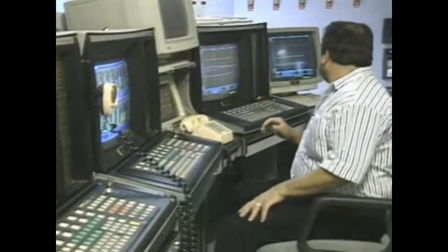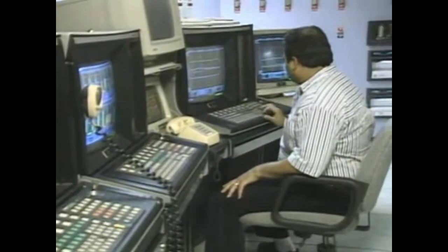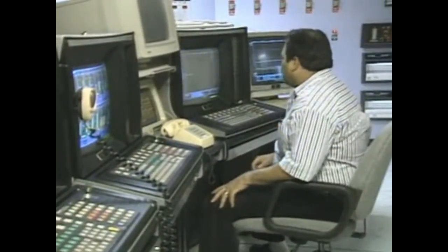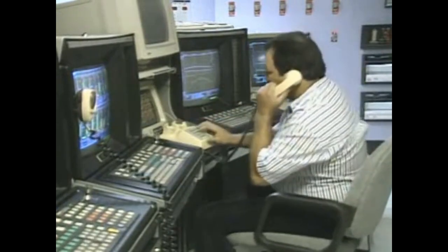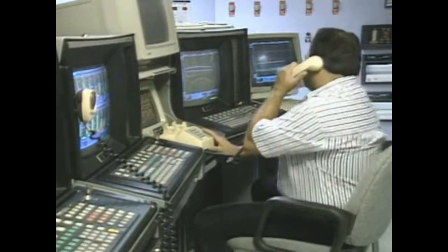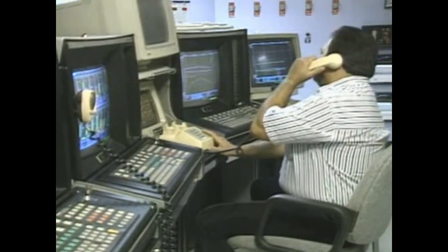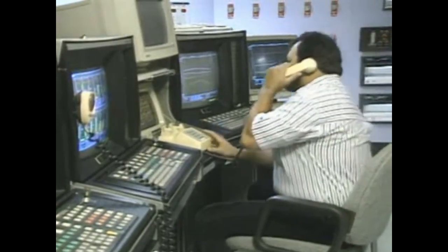While a distillation system sometimes needs to be taken out of service temporarily for repairs, it may also need to be shut down because of an emergency, and in some cases, an emergency shutdown can be similar to a short-term shutdown. For example, some emergencies require only a brief shutdown. Once the problem has been dealt with, the system may be returned to operation. But the basic goal of any emergency shutdown is to reestablish safe operating conditions.